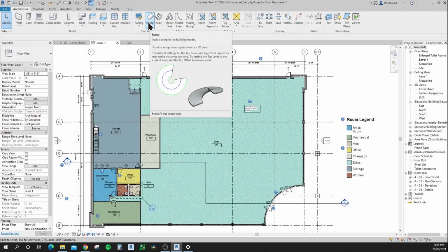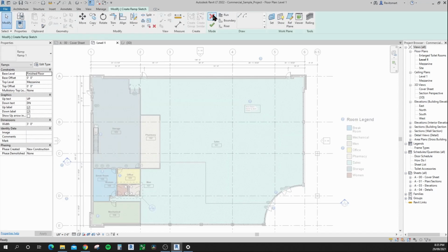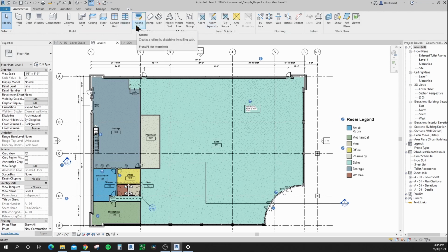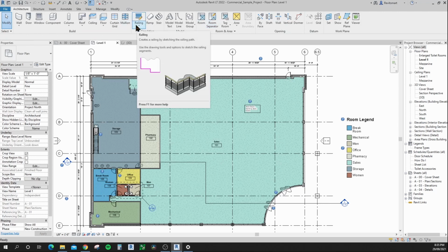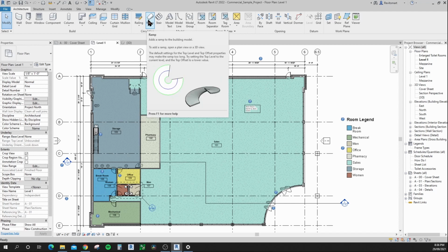Yeah, so ramps are kind of a mix between stairs and floors. With the ramps, you can actually give them a maximum gradient. So you can say that this one's only going to go for 1200 and it's going to be at 1 in 40, or whatever the requirements for that ramp are. If you're actually going to put some ramps in jobs, it's much better to put ramps in rather than just floors, because they are built with a purpose. With floors, you'd just be modifying them to suit your purpose, really.